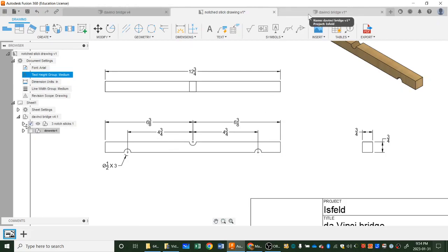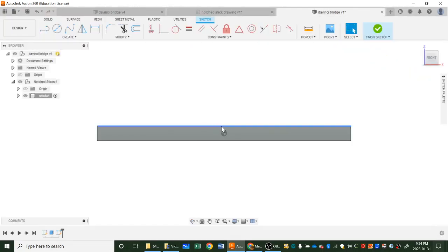So I'm going to go back to this. I'm going to go back to drawing my circle. On the edge at middle, click and pull. And 0.5 is my distance. Push enter. Now, the other circles come on the other side here, and I'm just going to draw them anywhere for now. I'm going to push circle, and I'm just going to click on that edge, make sure you're referencing the edge, and then pull out and key in 0.5 and hit enter.